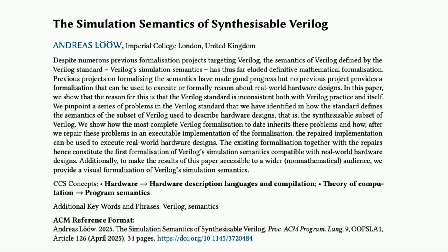If you simulate your circuit and it doesn't give you the answer you want, don't worry, run it on a different simulator, it might work. So his solution is, let's repair SystemVerilog semantics by trying to modify the standard to make it sensible. And so the always blocks I showed you, they were sane, well-behaved always blocks. In his paper, he shows you much more badly behaved always blocks. So if you wanted to torture yourself trying to understand the always blocks, you can look at his paper.